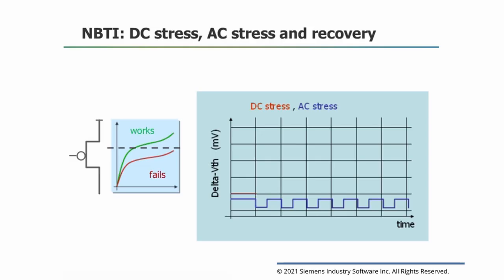Historically, NBTI was studied in depth under pure NBTI condition, that is, considering devices under their normal on bias, which is a negative gate-source voltage for a PMOS device. This was done without applying any drain-source voltage. In other words, with zero lateral field and thus no current through the device. However, further in-depth studies have shown that the presence of a strong lateral field significantly modified the PMOS degradation characteristics.